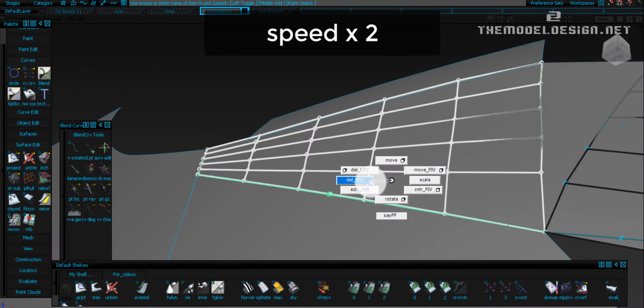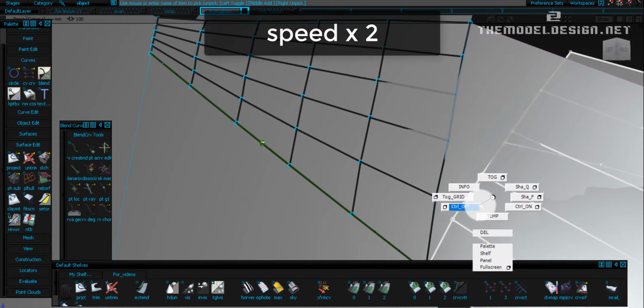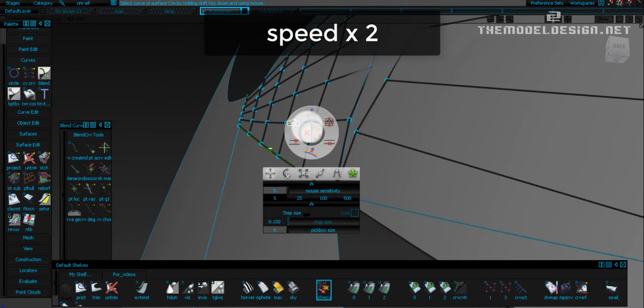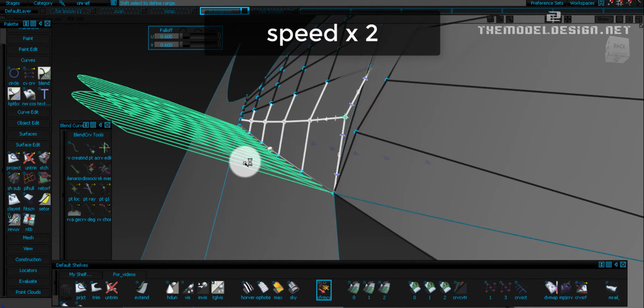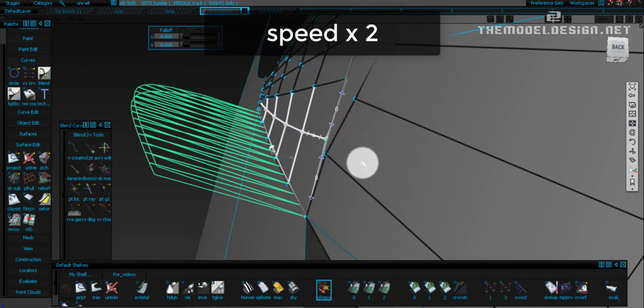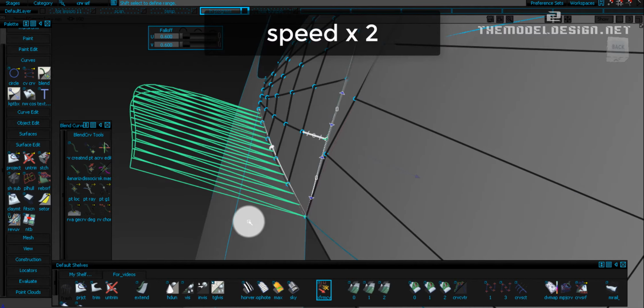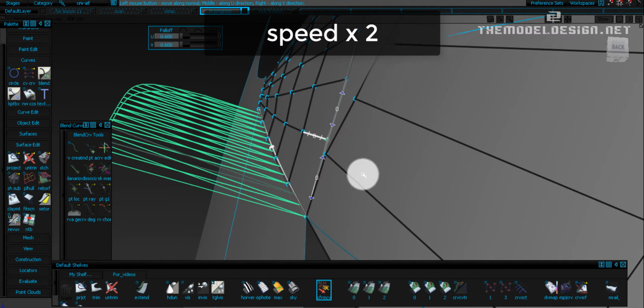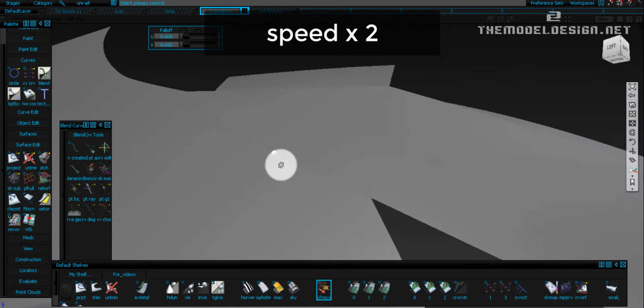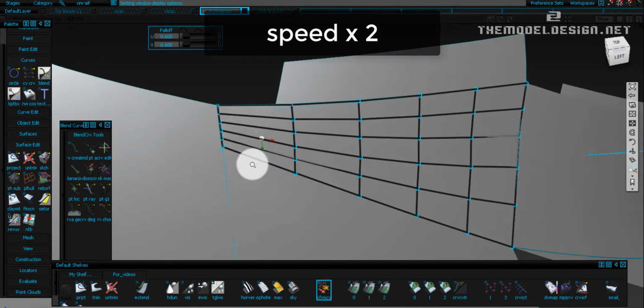Maybe firstly we could forget all the other holes of CVs and only work on the tangency G1 hole. We can first align G0 to the edge and then manually tweak the G1 CVs. Also, at the same time, we could measure the tangent break value, just like I'm doing it right now.